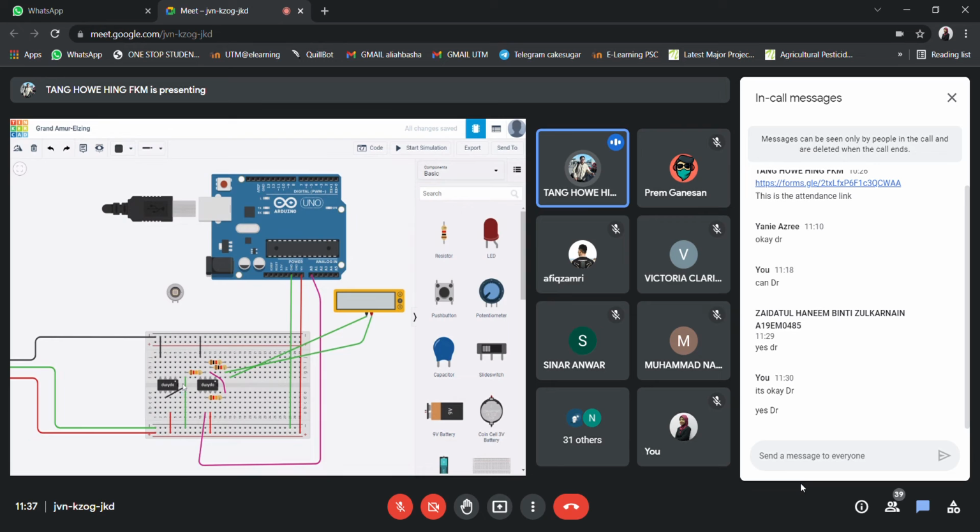The output comes to here, and then to this inverting input, let's say it's the orange color, and then this cathode goes to the ground, and the anode will enter the voltage follower. Then for this output, instead of a differential amplifier, maybe I'll use a non-inverting amplifier.